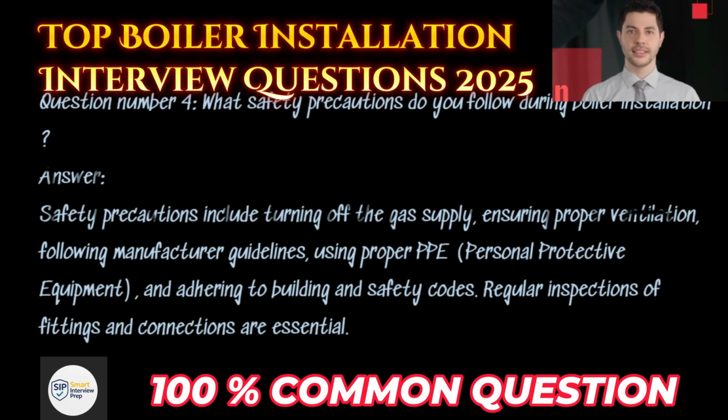Question number 4. What safety precautions do you follow during boiler installation? Answer. Safety precautions include turning off the gas supply, ensuring proper ventilation, following manufacturer guidelines, using proper PPE, personal protective equipment, and adhering to building and safety codes. Regular inspections of fittings and connections are essential.